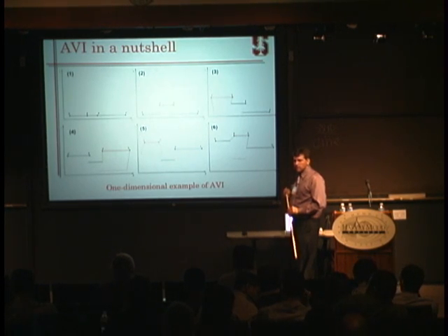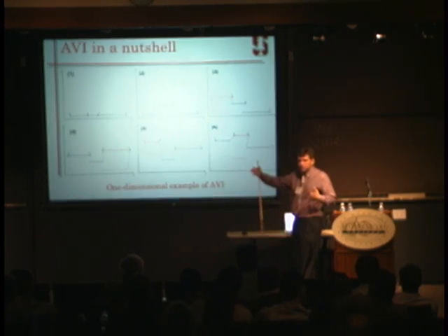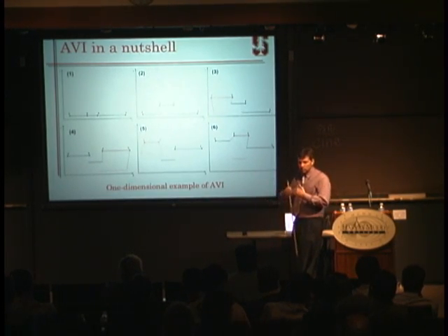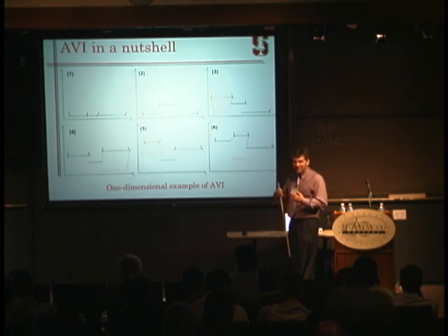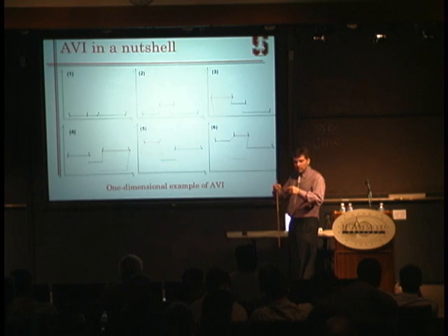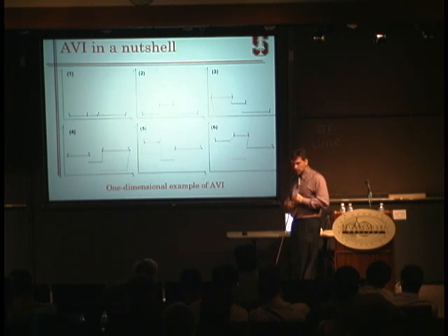It does make sense, and you have a continuum of methods of how implicit you would like to be. In the sense that you can solve the entire space-time region at once. You can solve 1 millisecond, 1 second. You just choose a space-time region that you want to solve implicitly, and you have to solve for all the elements at the same time, essentially.